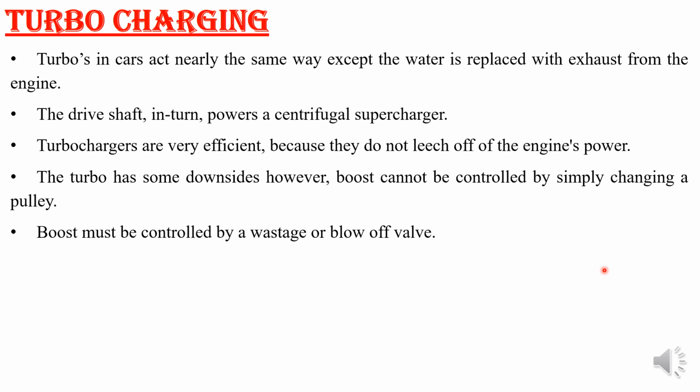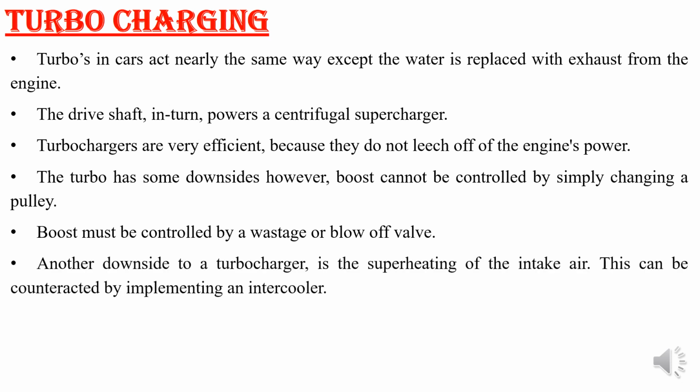We will call it boosting, because we can't go beyond 1.5 in the naturally aspirated engine. So how do we achieve that 1.5 pressure ratio? We can achieve it through the mass flow rate of the exhaust. That mass flow rate of exhaust is controlled by one valve, called the wastegate or blow off valve. Only through that valve are we going to control the turbocharger intake.